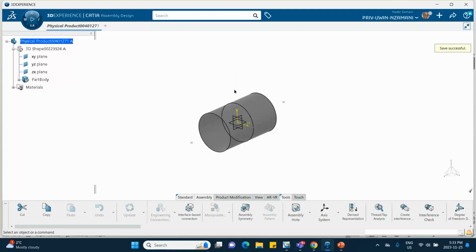Because I want to apply this sketch, I can hide it actually. Because I want to apply a force here, right there at that location, and I want to have a nice kind of a mesh. What I'm going to do is essentially partition this thing, divide it into 8 pieces. But the word partition is used for solid objects, so I'm going to split it. We don't really have partition for surfaces in the traditional sense. It is really just splitting it and keeping both sides, all sides if you want.